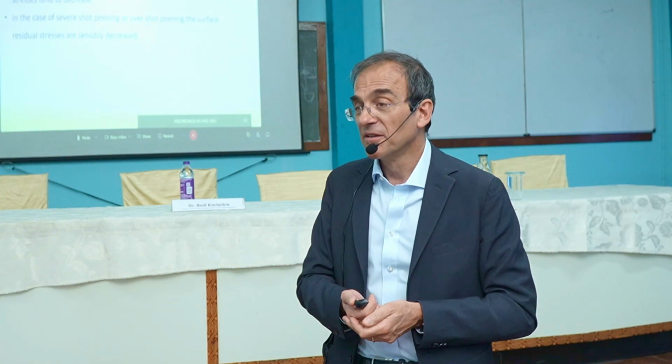But sir, in the case of XRD, we can get only the surface, right? So how do you get into the depth? With XRD, yes, we need to remove material, and we can do that by electropolishing or electrochemical removal of material. We must not use a mechanical tool, otherwise we are adding residual stresses and changing what we are measuring. We need to use electrochemical devices.